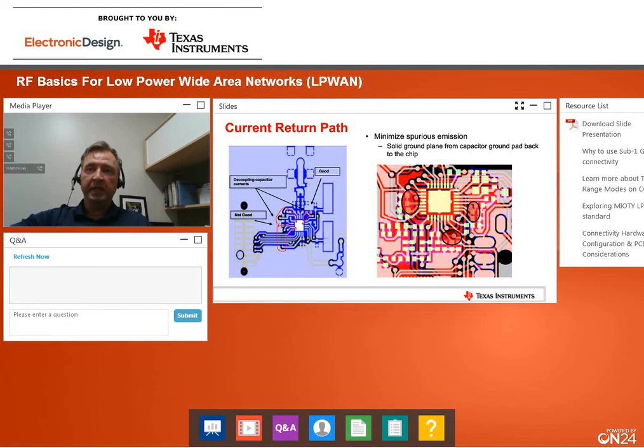And here's actually a multi-layer board, where somebody thought they did a great job, but then they cut out the ground plane in order to enable some kind of route on the back. These little bitty cutouts that people put in hurt the performance of these RFICs tremendously and should be avoided at all cost.